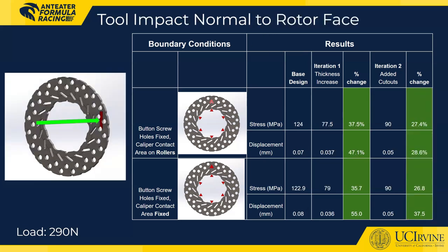We simulated a tool impact normal to the rotor face. This test showed that stress was significantly reduced with the modified designs, particularly the thickness increase, which lowered stress by 37%. Displacement also saw major improvements, making the rotor more resistant to localized damage.